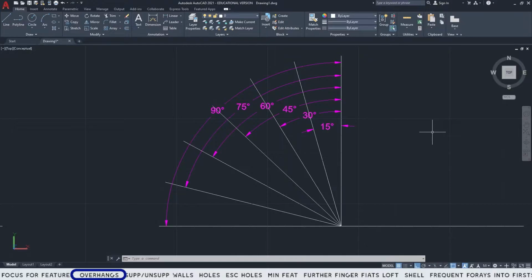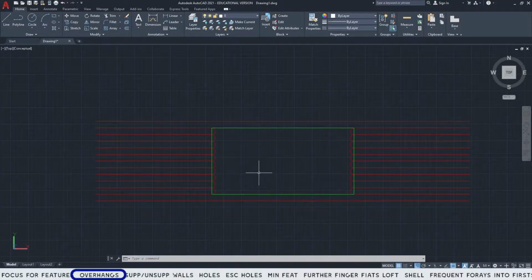Because each layer is moved over a little bit, there's some small portion of the layer that isn't laid down on anything. This part is the overhang. Toward the bottom, the overhang is hardly noticeable because its angle is practically vertical. Towards the top, however, the overhang is quite severe. To alleviate issues like this, you can change the shape to minimize the overhang to reduce or even eliminate supports altogether. Here are a couple of examples.